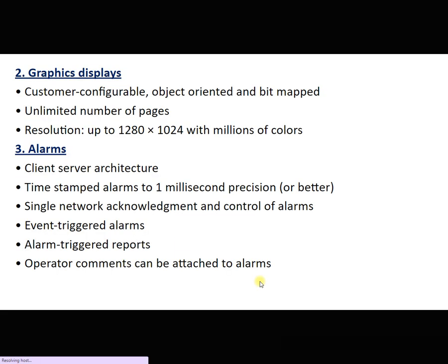Next, graphic displays. You can see it is customer configurable, nothing but user defined. Suppose I have one switch, I can represent it how I want: what color, what graphical feature, where to place it, and how to name it. In this way the user can define his own SCADA according to the field devices he has.